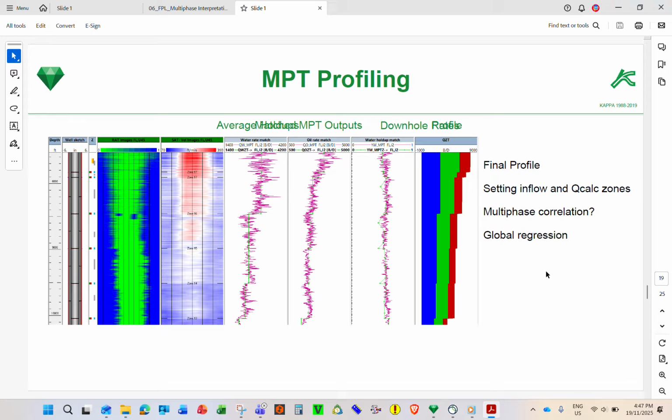But if you're going downhill, your water holdup will be smaller, occupied by the oil holdup. So if you are going downhill, you might believe more in the oil. If you're going uphill, you might believe more in the water. So you need to know the grade, the changing of the trajectory.